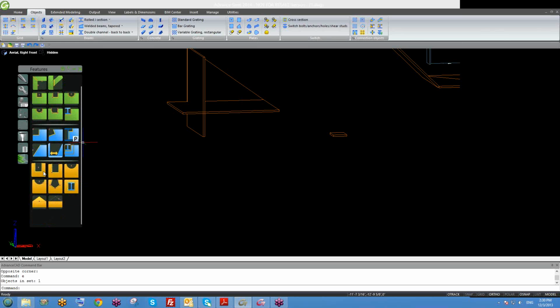These commands are exactly the same, and they do the same job as these 5 commands that we saw together. The only difference is you don't need to place the UCS. But these only work with plates, not for beams. Blue ones work with beams, and these yellow ones work with plates.